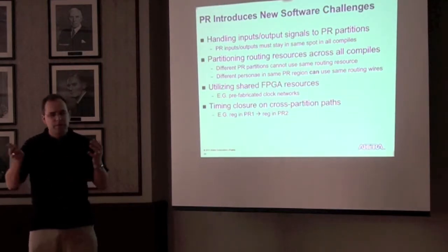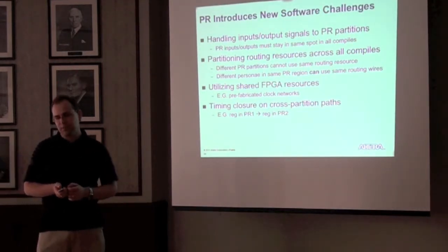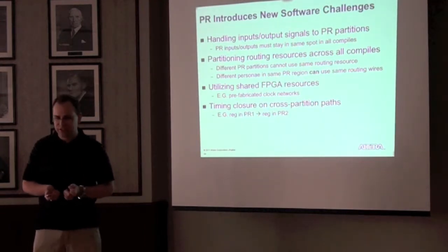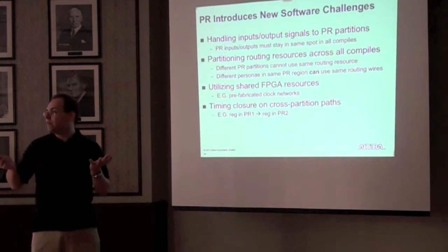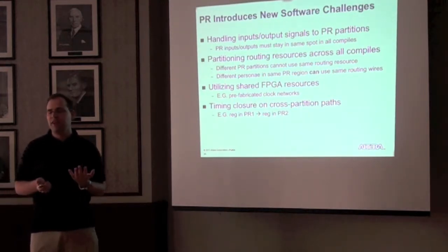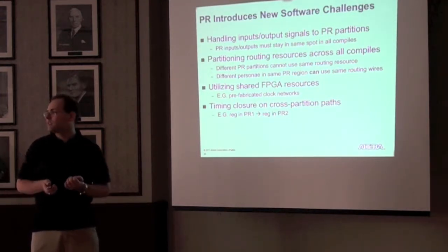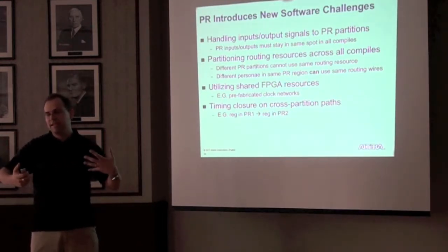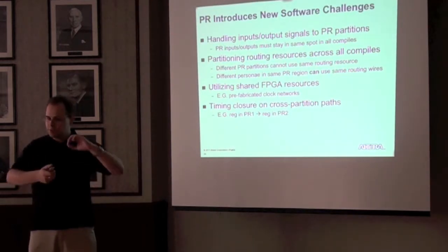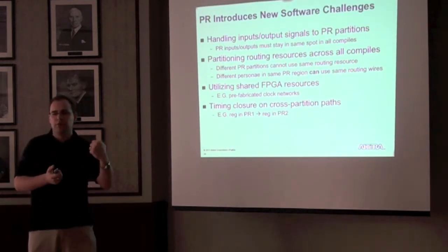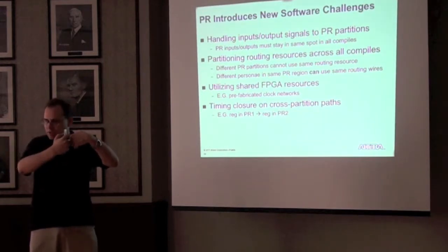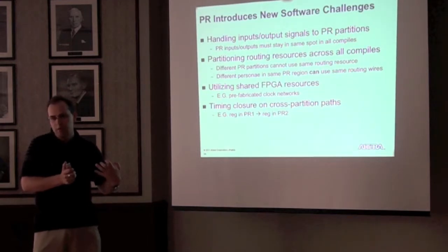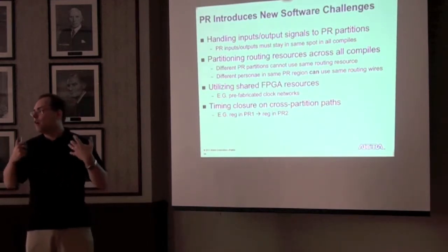So it's primarily the multiple compilation aspect that introduces new software challenges. I'm going to talk about 4 specific issues that we've had to face that may have become apparent to you. So first of all, we have to handle how I/O works in PR partitions. Basically, the part in the static region must stay in the same spot across all compiles, and there must be some sort of fixed point, whether it be a wire or a LUT, that can be counted on, such that when we change the chip's contents from one persona to another, the design automatically works.